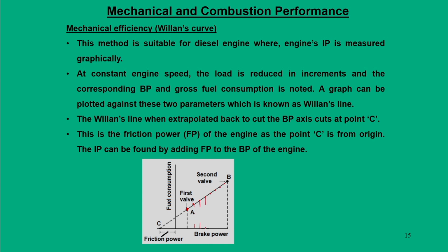So, we can generate this data experimentally. These are experimental observations in which we keep on increasing the fuel consumption and we get the brake power. Basically we get the curve AB from this experimentally observed data, and it will be treated as a straight line. Now, once you generate this curve, this is with respect to a particular engine. What you do is extrapolate this data from point A and see where it cuts the negative axis of brake power. So, this cuts at the point C.